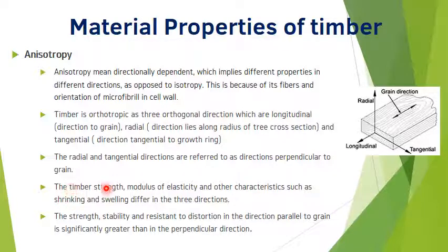Timber strength, modulus of elasticity, and other characteristics such as shrinkage and swelling are different in the three directions. The strength, stability, and resistance to distortion in the direction parallel to the grain is significantly greater than in the perpendicular direction.